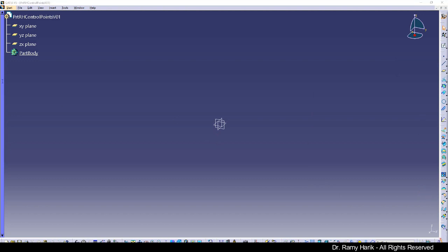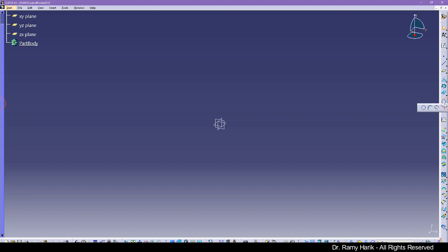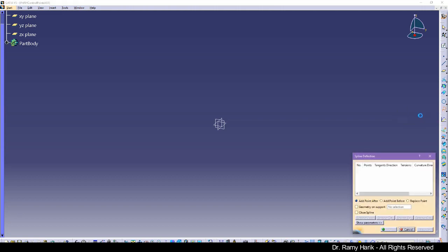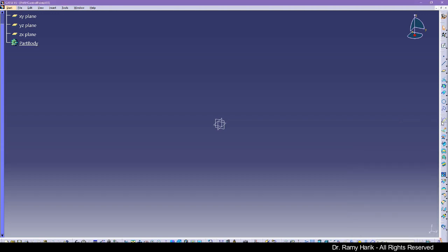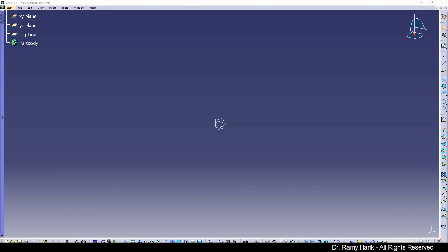So now that we have all the icons, what are the different icons that we have? We have the geometrical reference. This is in here where we create points, where we create lines. These are curves by operation, so you can project a 3D curve on a surface, you can intersect two surfaces, and so on. This is for a parallel curve on a surface. In here we can create different types of connections between curves, and so on. This is for a helix, or if we want a general spline with a 3D point, and so on. In here we can create surface operations, and then we can cut them. This is what we have just done in the first part of this tutorial.